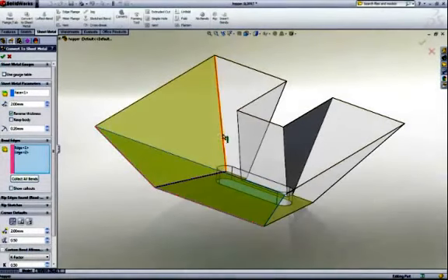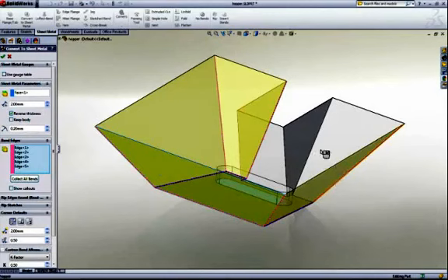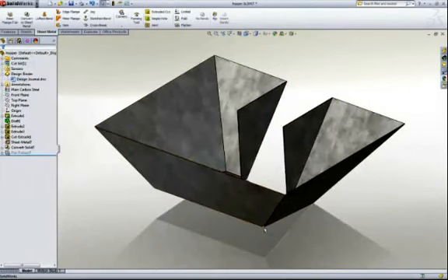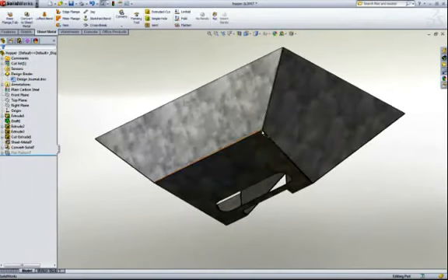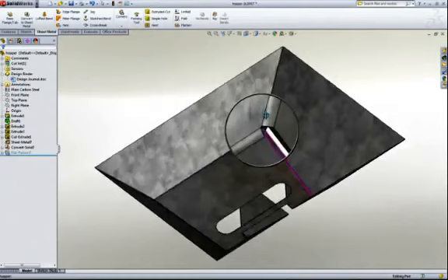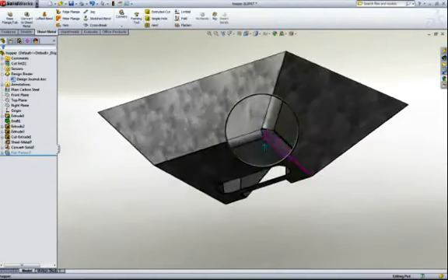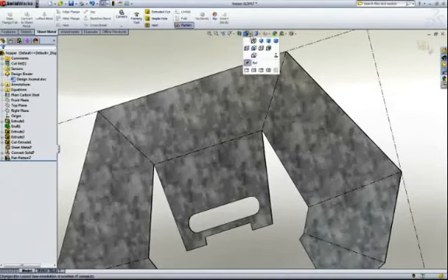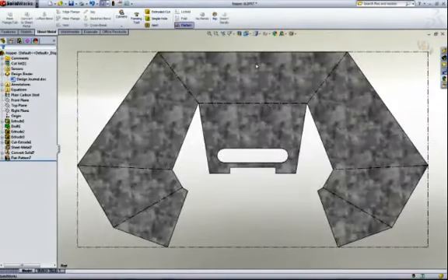Start with a fixed face, then choose the edges where you want bends. SolidWorks intelligently adds rips to the adjacent edges. Material can be added inside or outside of the selected face, and all sheet metal parameters can be adjusted. Notice the nice job SolidWorks has done in corners where these compound angled faces come together. Regular sheet metal features can be added, and of course these parts can be flattened and readied for fabrication.